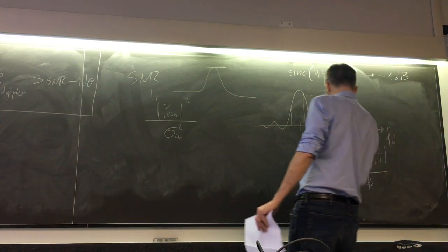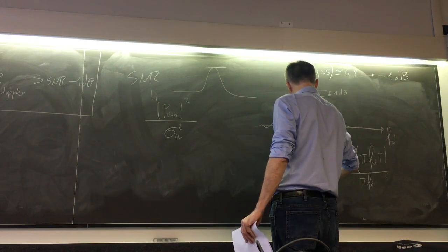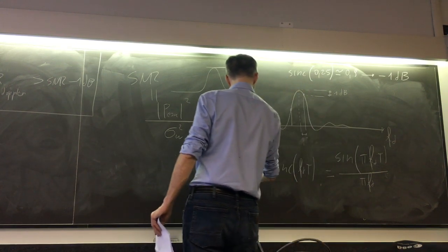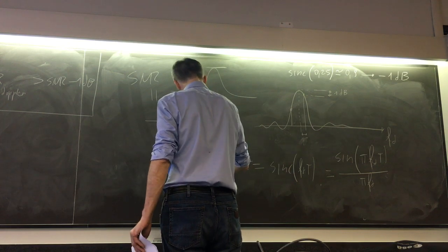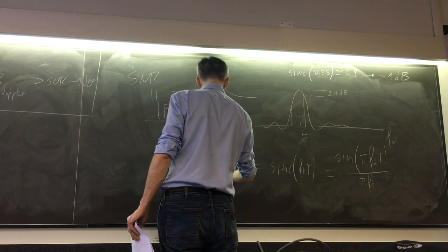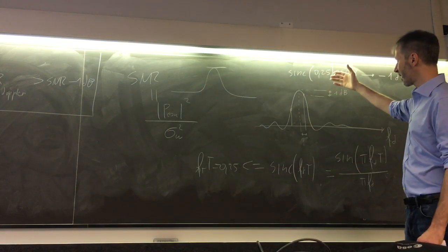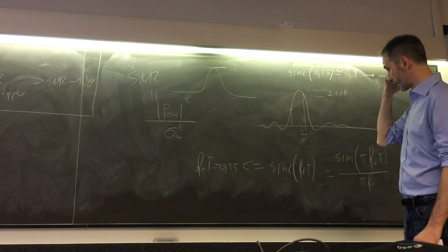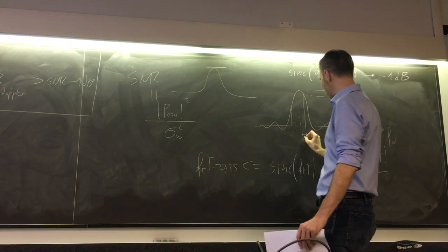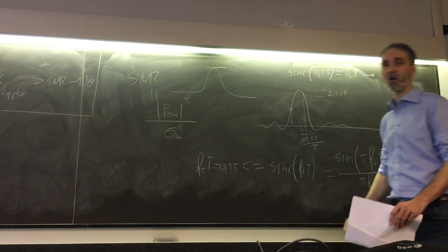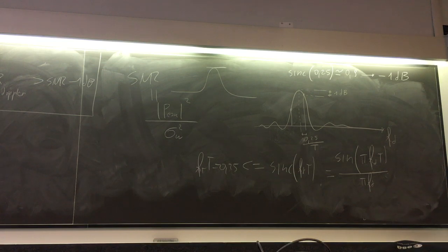This is equal to the cardinal sine, fd times t, and so we are requiring fd times t be equal to 0.25. So you are requiring that your frequency does not deviate from the true frequency by more than 0.25 divided by the length of your pulse. Sorry, I made too many passages at once, but I hope that now it's clear.